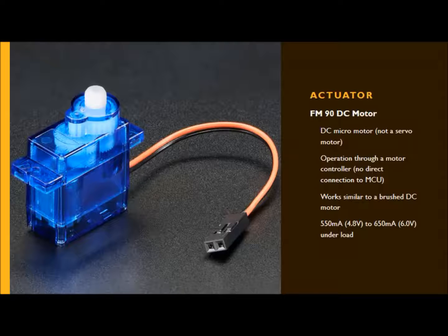The motors in this project are the actuators. The ones used in the Voco are the FM90 DC motors. These are not servo motors, they are micro motors. Operation is done via a motor controller. They are designed to work similarly to a brushed DC motor. The working range under load is 550 milliamps to 650 milliamps between 4.8 volts to 6 volts respectively.